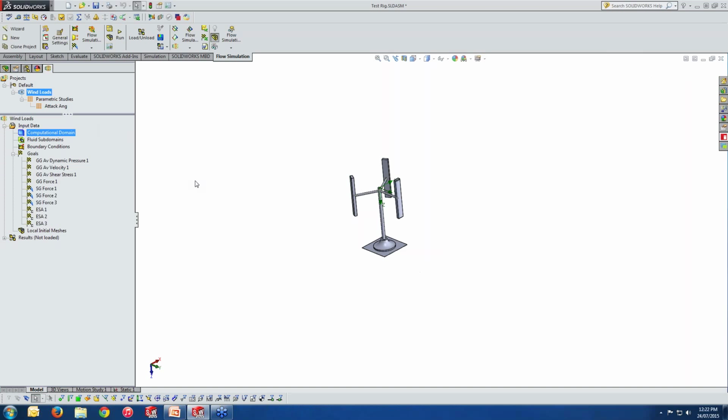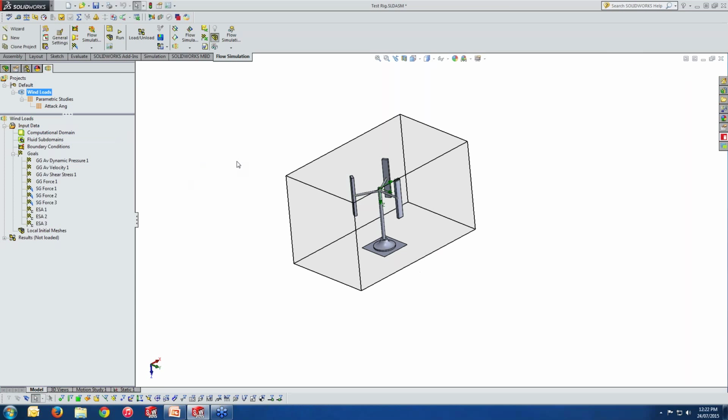So, at the first instance, we have decided about our wind tunnel. Well, inside this wind tunnel, the initial conditions are simply governing. We have atmospheric pressure, we have a temperature of 20 degrees centigrade, and also we have 12 meters per second of wind flow, which we said is air coming here. That is almost setting up our case.